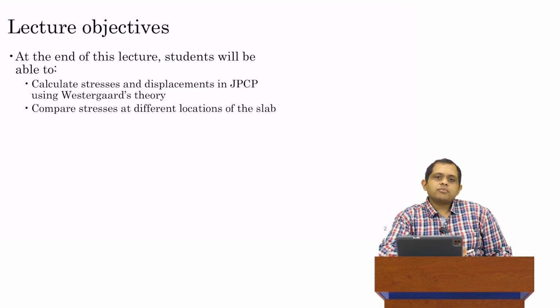In rigid pavements, what we saw is the problem with that assumption is that JPCP consists of a discrete set of slabs which have a finite length and a finite width, typically 3.5 to 4.5 meters. Now, while that is certainly much larger than the thickness, it is not as large as, say, a flexible pavement. And so, if we want to take into account that we have these finite size slabs and we don't have an infinite size slab, then layered elastic analysis no longer works.